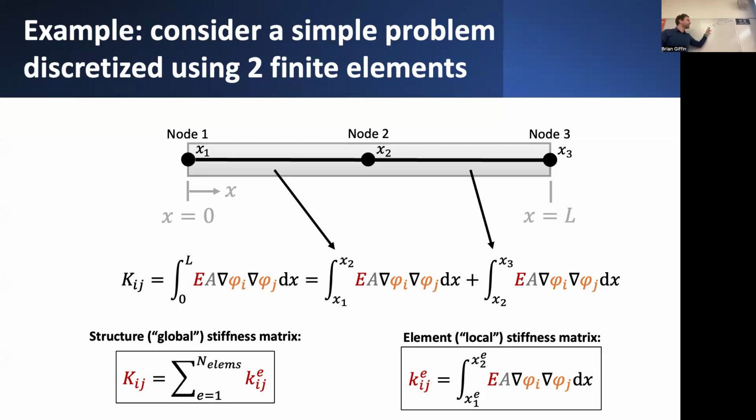So a total of four nodal basis functions would we have to construct in order to actually interpolate these different values. And certainly, in order to do that, we would need something more than simply a linear function to pass through all of these different points. We'd need some higher order polynomial. And nominally, we would need as many orders to that polynomial as we have these discrete unknowns that we would have to interpolate. So in that sense, coming up with extended expressions for the stiffness matrix really depends on the order of this interpolating polynomial that we're dealing with in constructing these expressions.